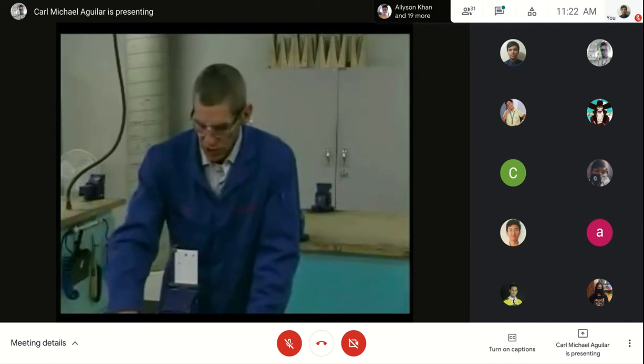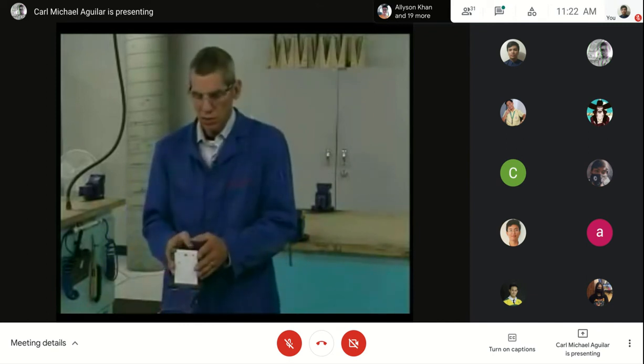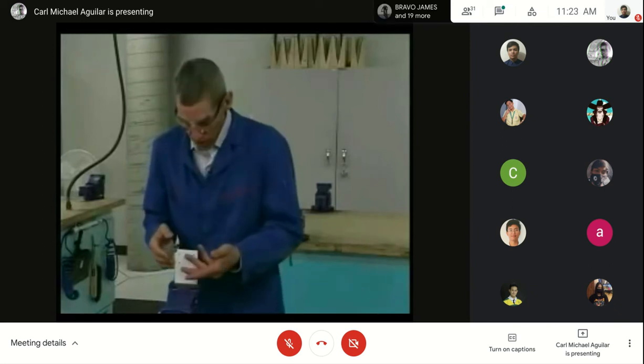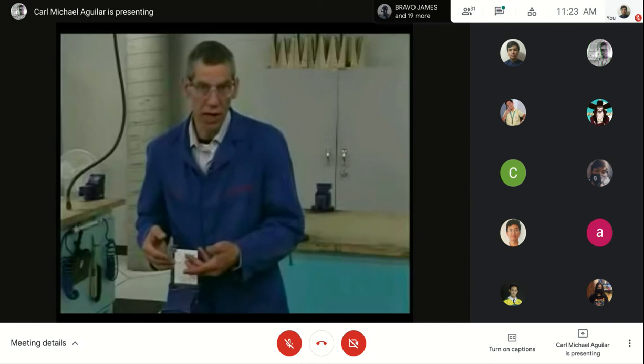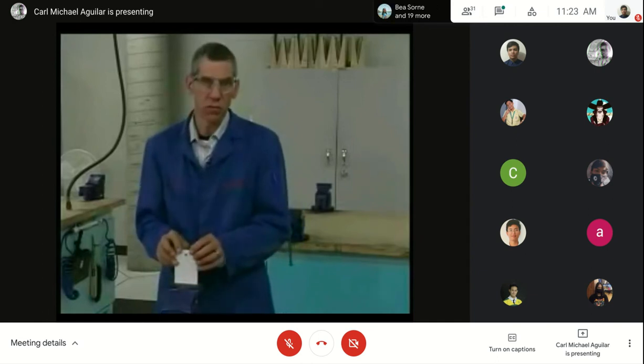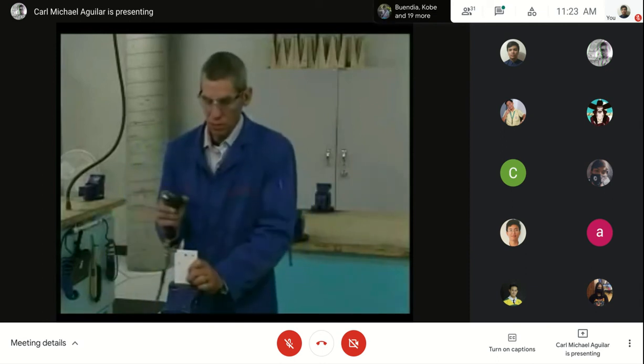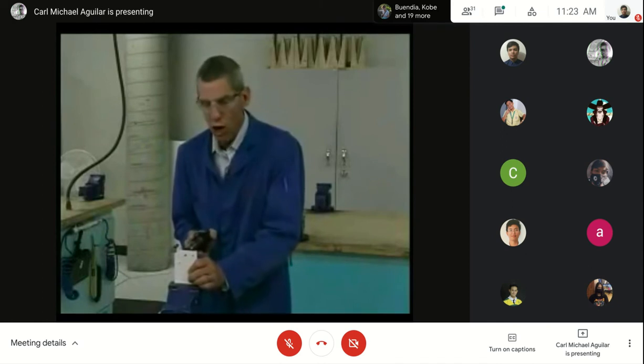Now, the inspection criteria is basically in 3 categories. I inspect the manufactured head for damage. I inspect the shop head, the one that I've just formed, for damage. And I inspect the sheet for damage. The manufactured head can get damaged if I am not pushing hard enough on the rivet gun.